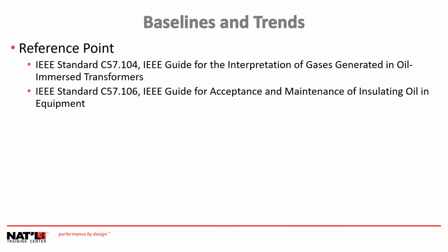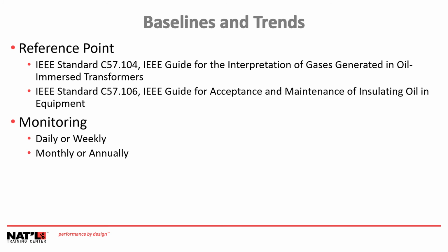Establishing a reference point for gas concentration in new or repaired transformers and following this with a routine monitoring program is a key element in the application of gas analysis. Any owner with liquid-filled transformers should own a current copy of the IEEE standards associated with insulating fluids. Monitoring and health and serviceability of a transformer must be done on a routine basis and can start anytime. It is not just for new units.